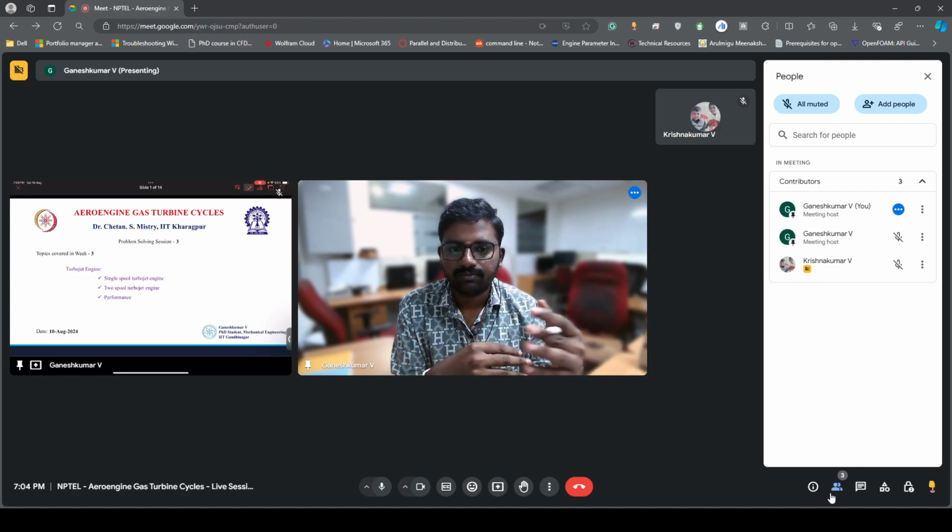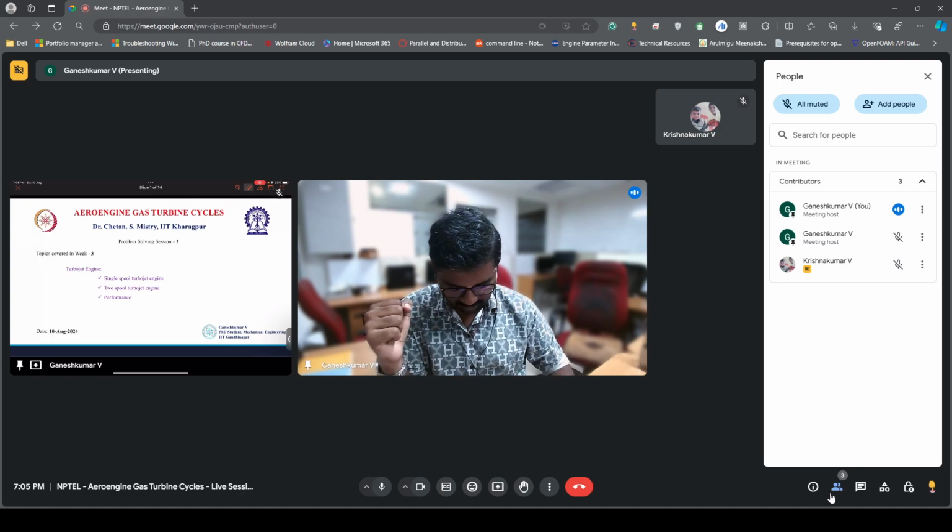For example, pressure ratios, turbine entry temperatures, Mach number, mass flow rate, all these things, and how they are affecting thrust, TSFC, efficiencies, also specific thrust, right? So that is what we covered in the week three lectures.